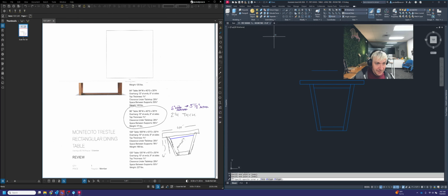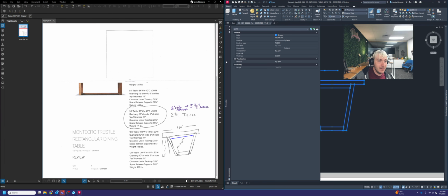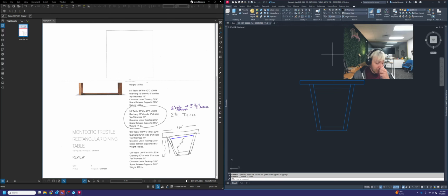So I just drew a line in. I highlight all that again. You'll see it says all quantity 7. And if you click on that, it'll say there's 1 line and 6 polylines. You want to get it down to only seeing polylines though. So you want to get rid of any excess geometry that doesn't need to be there for this.